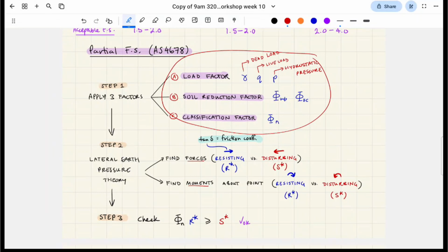So this isn't quite geotech design. It basically makes you exaggerate the loads that are acting on your structure and reduce its capacity by a little bit as well, right? I'll give you an example. Say you're designing scaffolding, maybe it looks like this, and you're designing it to hold 3 tradies. Say these tradies are kind of heavy. They all weigh about 100 kilos each.